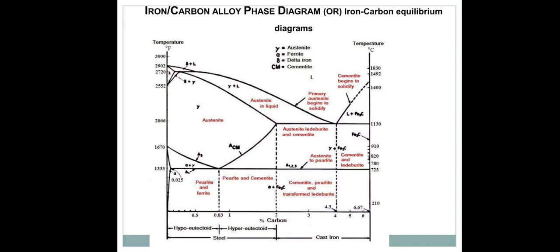It is formed by decomposition of austenite when cooled at a rate slower than that which will yield a troostitic structure, and faster than that which will produce a pearlitic structure. With sorbite, steel is slightly less ductile than pearlite steel. Its tensile and yield strength are high. Thus, sorbitic steels are often known as toughened steel.